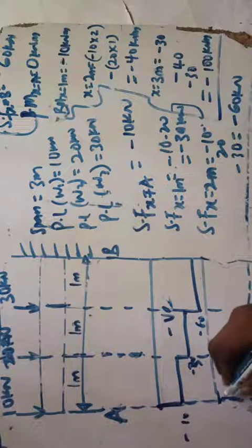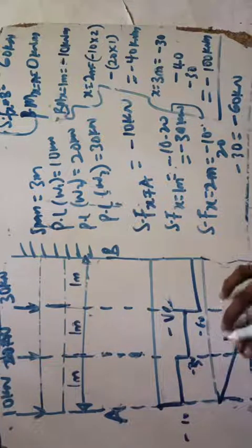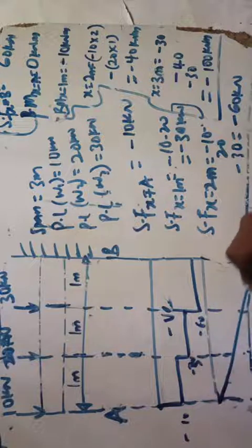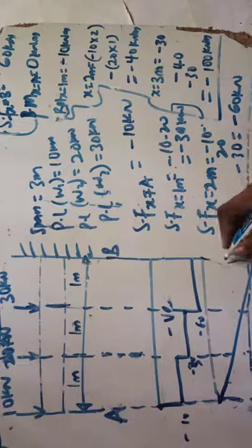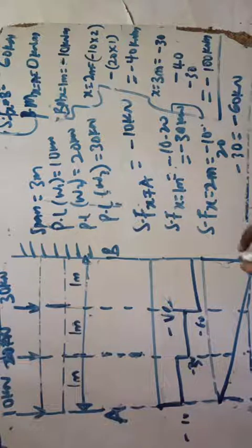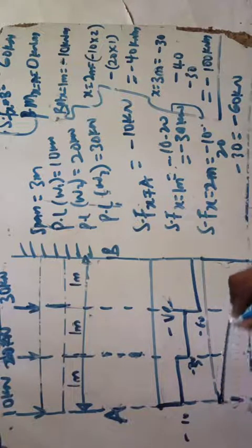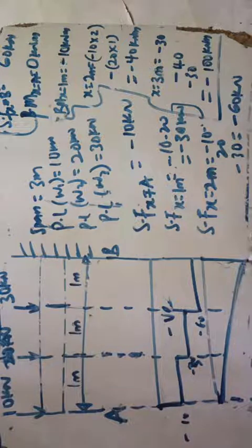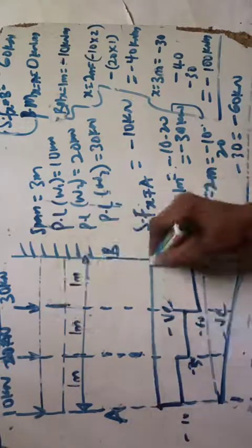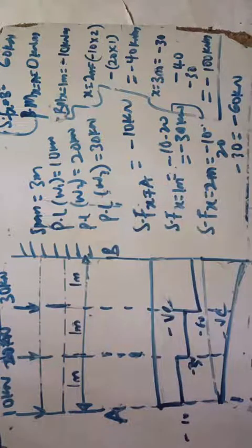It will decrease accordingly, minus 40, and I will just have it as this. You have it as straight, no slant, nothing, that's straight, and that is negative. Okay, so that is the shear force and bending moment diagram for this kind of load for a cantilever. Okay.